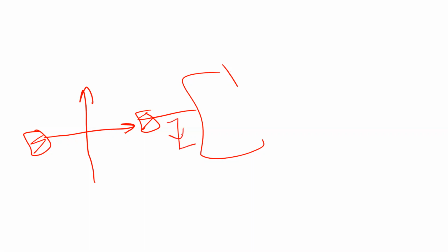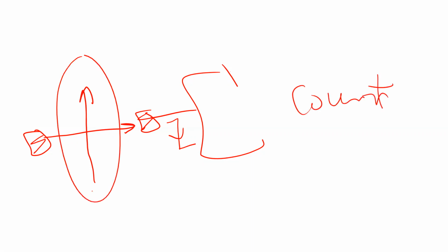For example, you have here a sensor, and you have another sensor here, which is infrared transmission light. So this is infrared light, and this is a receiver. Every time someone enters a store, or someone cuts the light here, you generate a pulse here. This pulse is going to trigger an interrupt. In this case, I use IRQ interrupt to count. I want to count the number of events, how many times this event has happened.